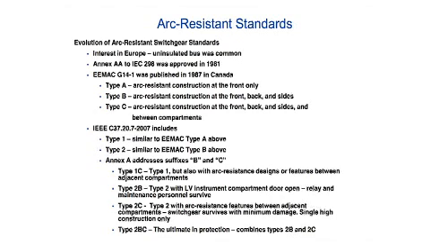The issue here is that when you open up that door in normal switchgear, it's just like opening up a breaker door. If you have an incident that occurs inside the switchgear, that same amount of gases and destruction are going to hit you the same way. So in 2B construction, we isolate the low voltage cabinet totally. And what does that mean?